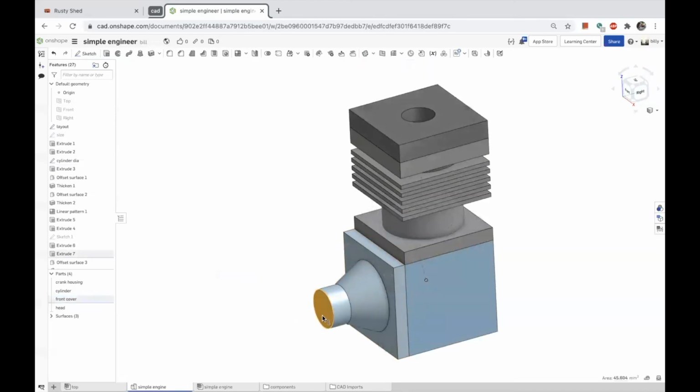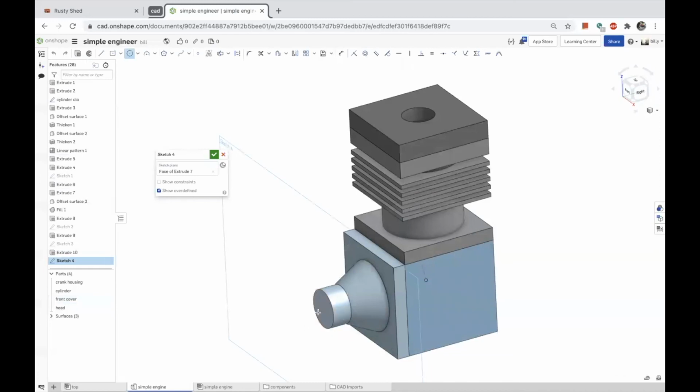Let's exit out of the context. We'll grab that, create a circle. Boom, boom. So what's my reference? My reference in this point is this edge. Okay. What's my reference? My reference is the origin and I'm vertical to it. So right now I have a choice. Do I want to work off of the origin or do I want to work off of this edge? I'm going to keep it local.